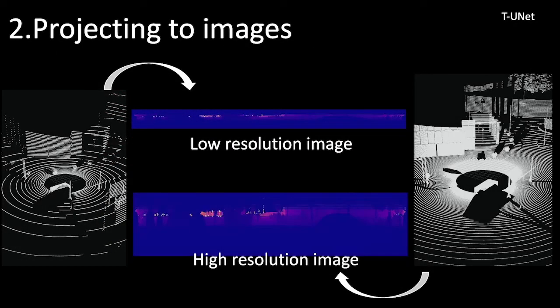The point cloud of LiDAR is a kind of non-Euclidean data that has disorder and variable number characteristics. Therefore, the point cloud needs to be Euclideanized to use neural network models. The point cloud can be converted into voxel, graph, and other structures. But considering the real-time requirements for autonomous driving, it is a more reasonable way to convert the point cloud to an image.